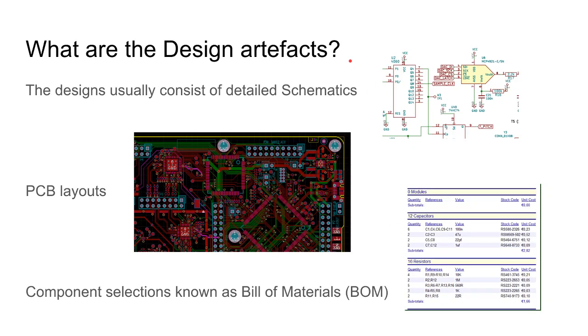So second question is, what are design artifacts? When you talk about hardware design, there's a few steps involved. First of which is a schematic. Now a schematic is an electrical schematic. How can one explain that? It's basically an overview on how all the various parts are connected, specifically each particular pin on the microchips or resistors or components, and how they're connected to the other components.